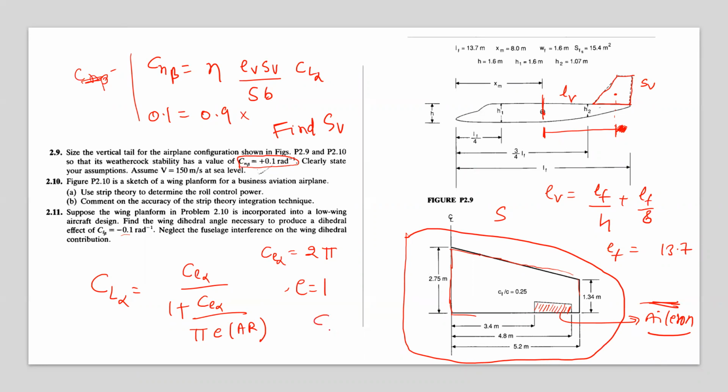That derivative is nothing but C_L delta A, where C_L means the roll moment. How much does it change with respect to delta A? This basically means differentiate the roll moment with respect to delta A. Your job is to find out this number using the given geometry and some assumptions on the wing.